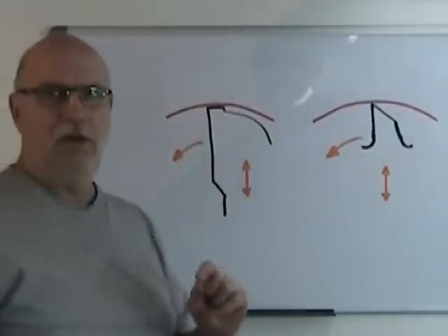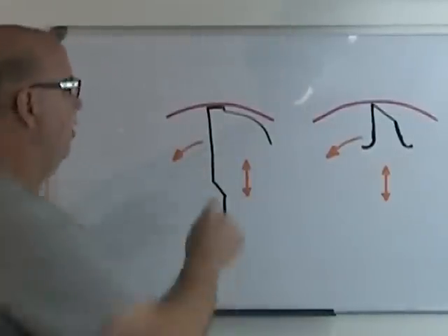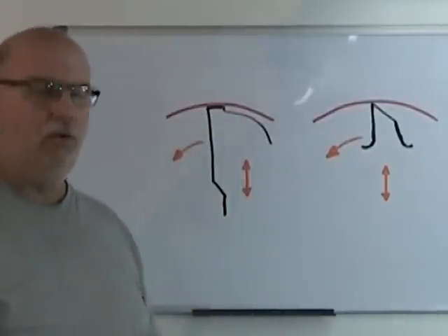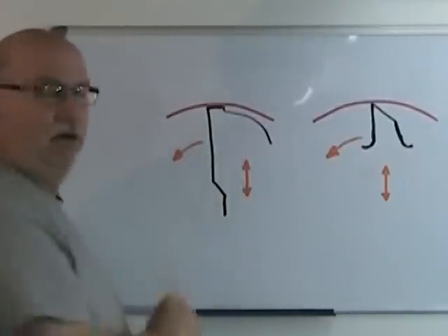So they have to be sharp, but they are not cutting edges. We want that edge to be able to rub without enlarging the hole. Why? Because we're center cutting.